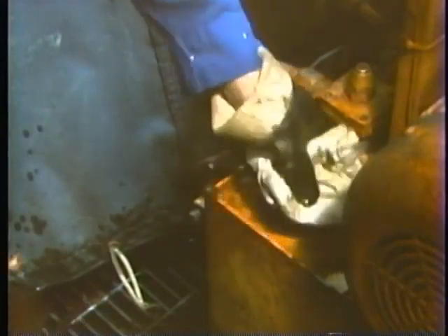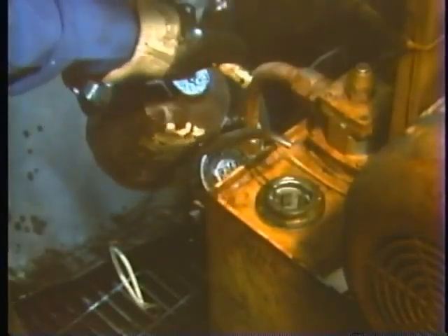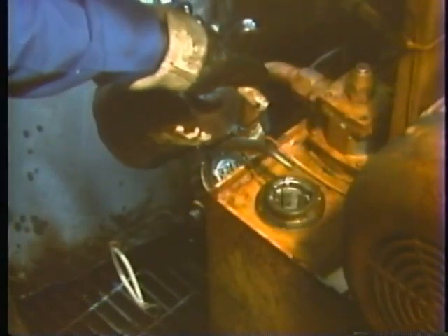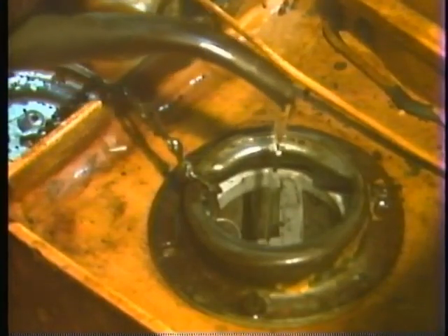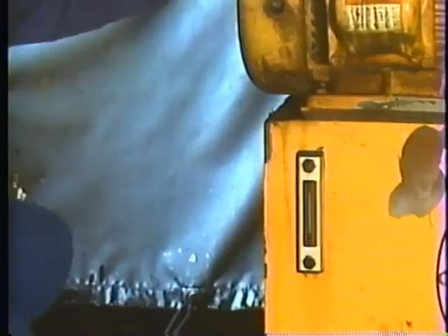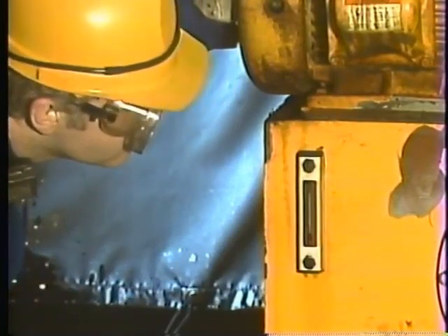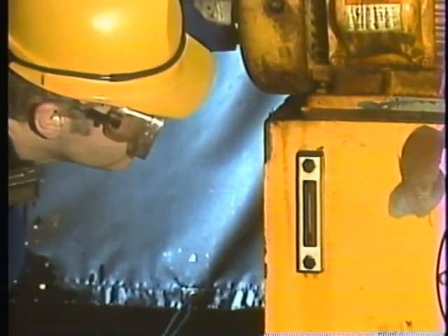Before hydraulic fluid is added to a reservoir, the area around the filler hole also should be cleaned to avoid getting dirt or other contaminants in the fluid. Some filler holes, like this one, may contain a screen to trap contaminants. Maintaining the proper temperature of the fluid in the reservoir is also important for effective system operation. In this example, the operator checks the fluid temperature on a thermometer within the sight glass.